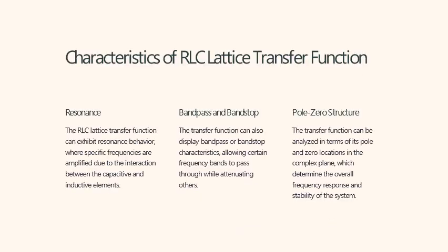Characteristics of RLC lattice transfer function: resonance, bandpass and bandstop, and pole-zero structure are the three characteristics. Coming to resonance, the RLC lattice transfer function can exhibit resonance behavior where specific frequencies are amplified due to the interaction between the capacitive and inductive elements.